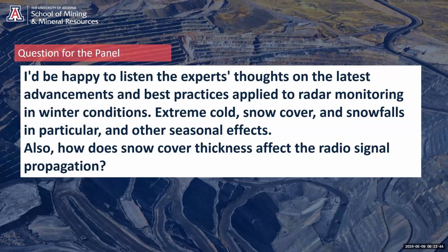And finally, in general, if the snow is accumulating on the surface, the radio signal may penetrate a little bit of the first centimeters of snow. But if the snow is growing, basically, you will see movement towards the radar. When the snow melts down, you see movement away from the radar. So we try to focus as well on the crests of the benches with high coherence to conduct analysis in those scenarios. Thank you.